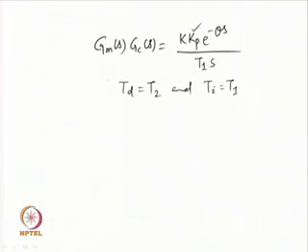Thus, the two parameters of the controller, Td and Ti, have already been designed or chosen based on the time constants of the process dynamic model. Okay. So, I will now try to find an explicit expression for the proportional gain associated with the controller, Kp.